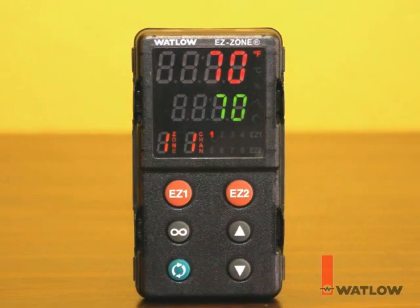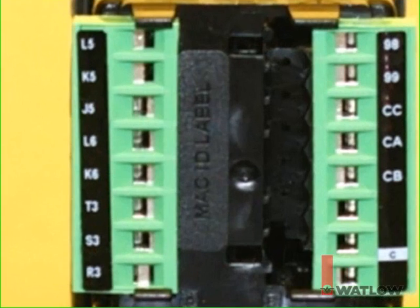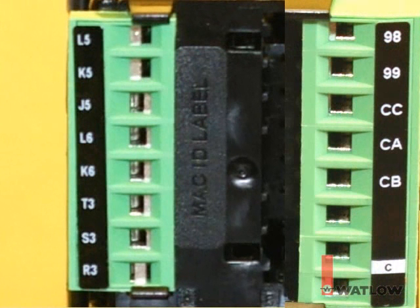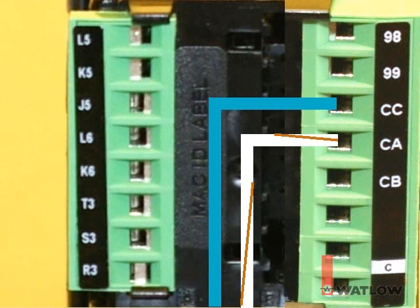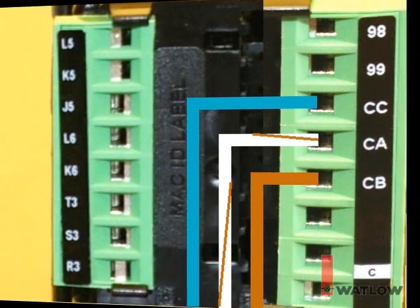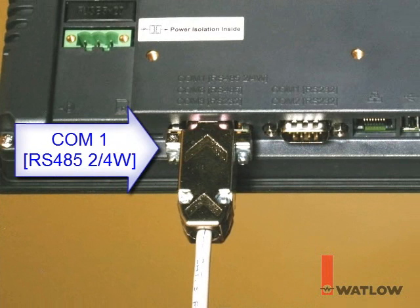Next, we need to connect the PM to the OIT. If you're using the cable available from Watlow, connect the blue wire to CC, the white with brown striped wire to CA, and the brown wire to CB. Connect the DB9 end of the cable to the COM1 485 connection on the OIT.